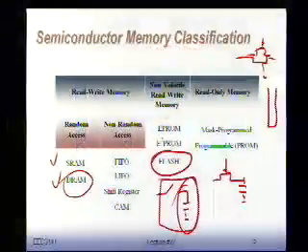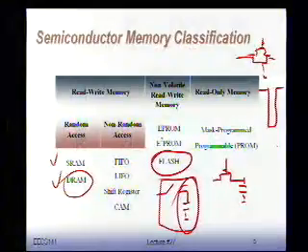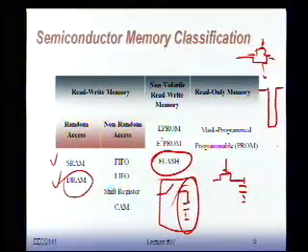That takes area. We don't like that because what sells in memory is how many memory cells you get. Density is the most important thing in memory design. Above performance, above power, well, power dissipation is not really true, it's becoming an issue. But people always try to make the memory cells as small as possible. So in order to make large capacitance in a small area, what people have done is go three-dimensional. Like, for instance, if I have a piece of silicon, I can etch a trench using dry etching, plasma etching.